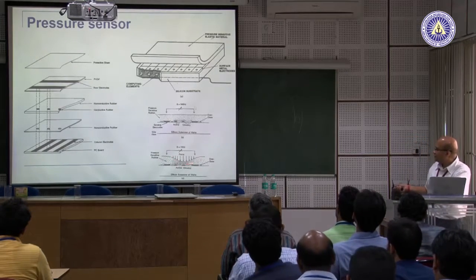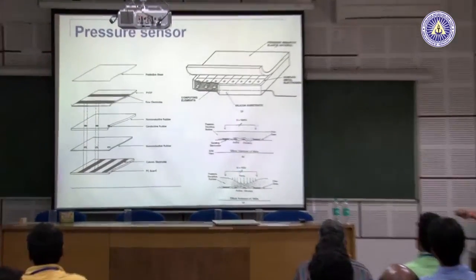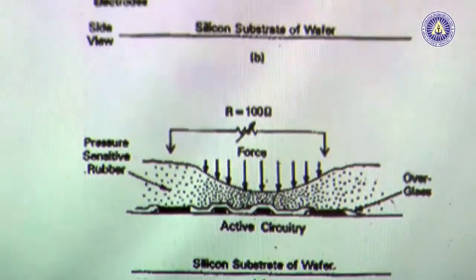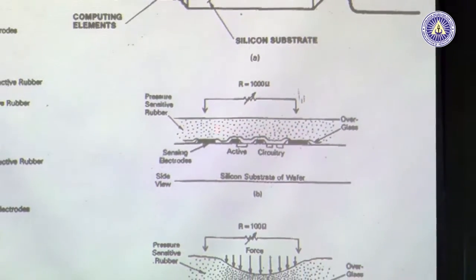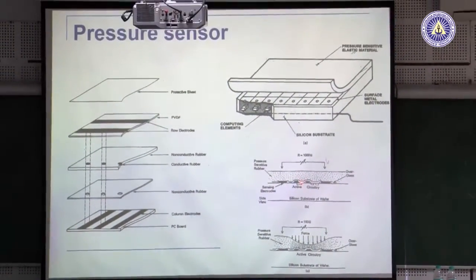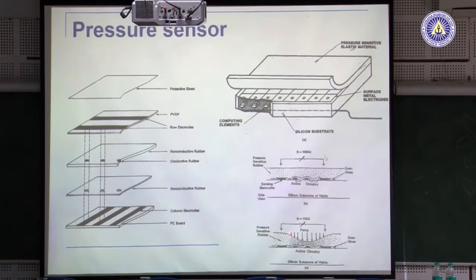Okay. So, how pressure sensors work is essentially we have different electrodes. So, these are the electrodes, and there is a layer of conducting rubber in there. Okay. So, in the normal condition, charge will not flow through this, because there is an air gap which is an insulator. So, what would happen is if I press it here, say for example, by putting our fingers here we are pressing it, then some of the rubber is getting in there. If the rubber gets in here, it will short.